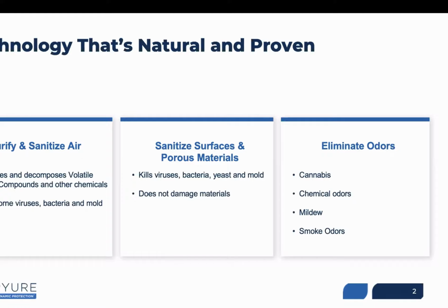What it does is react with everything around it. HO or OH is a very unstable oxidant that is striving to become water again. It's looking to bind with another hydrogen, which it may do in the atmosphere. But more often it reacts with organic VOCs present in the space, which is how we eliminate odors as well as other products in the area.